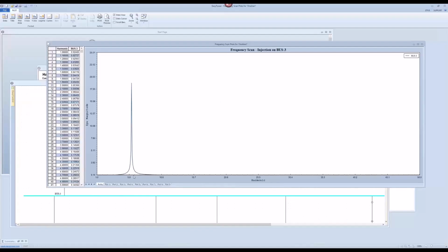But in some cases, if you have, let's say, harmonic current injection at the 5th order, 6th order, then you will have a high oscillation problem, high voltage, high VTHD problem, right? So it depends on the spectra of your injection, where exactly you have the problem, and the system characteristics about where exactly your resonance point is. You do not want to put your system resonance point right at the largest amount of the harmonic current injection place, right?